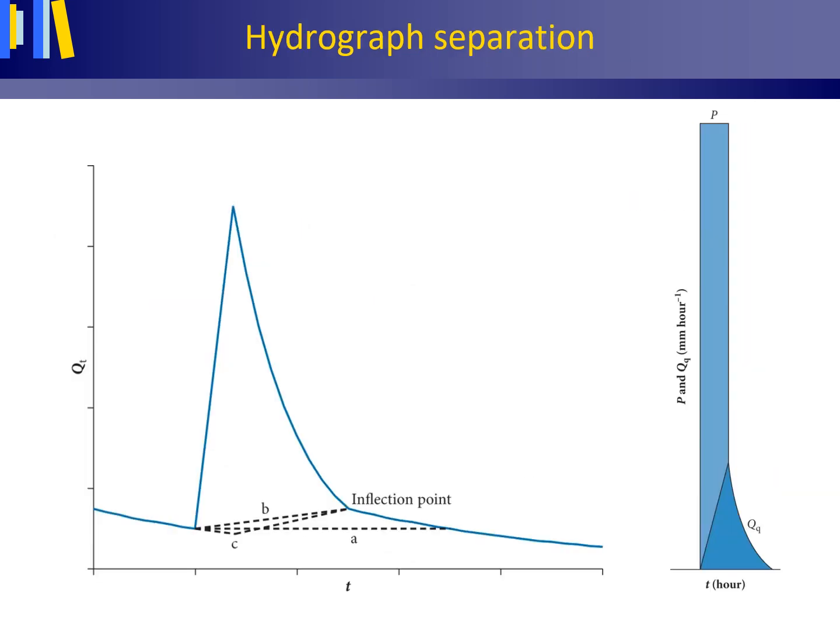There are many methods for hydrograph separation into quick flow and base flow. All methods have in common that they are unavoidably arbitrary. Importantly, one should always stick to the method one sets off with when analyzing hydrographs, or else the comparison basis is lost.